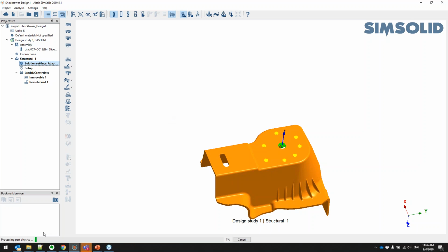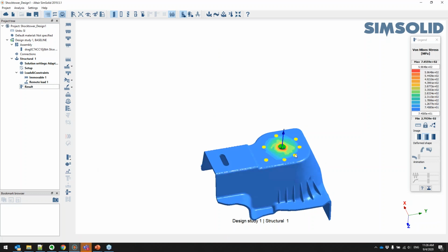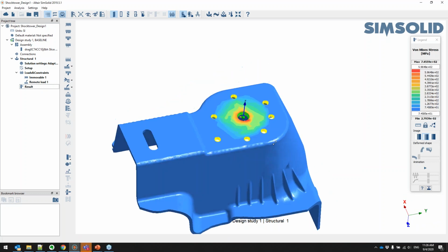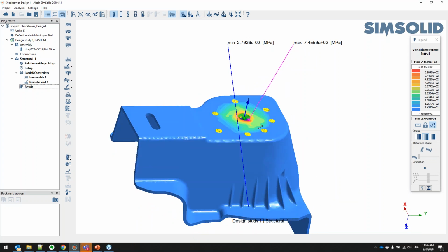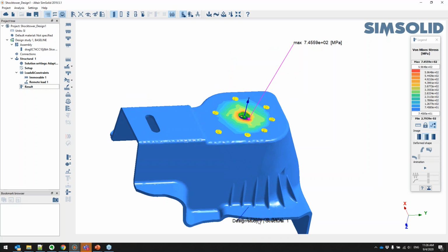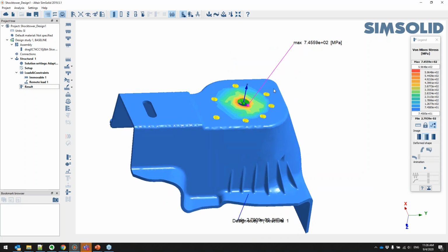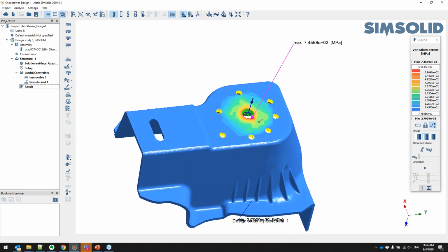All right, so you see, it evaluates the geometry, 3 passes, 1, 2, 3, and plotting the results. Okay, so then you can go and check what's the stress here. Okay, this is the stress, high stress is there. Use this to immediately see where's the high stress. Okay, and then so minimum stress here, and then high stress. Okay, so let's say this is where you're looking at.